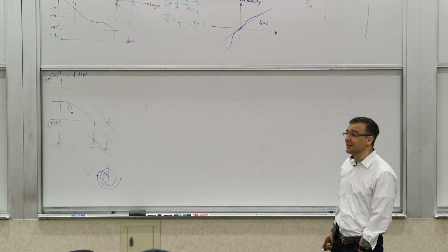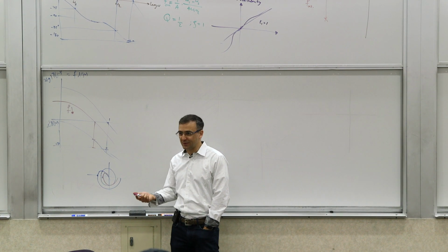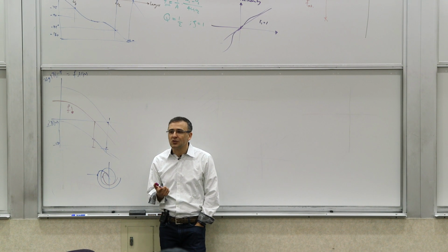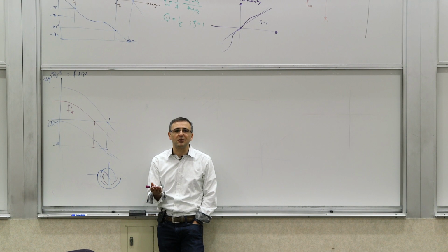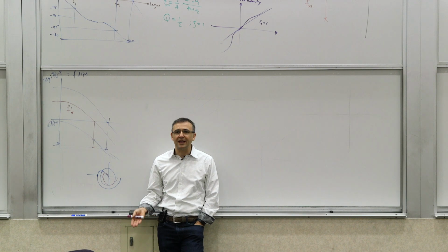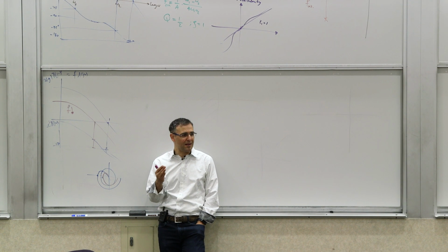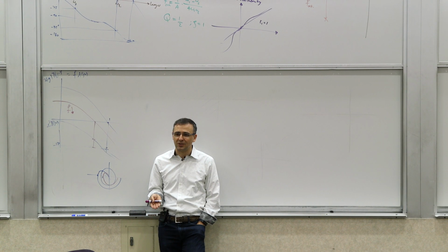Well, you get more gain. You might get more closed loop gain. You get less loop gain. That's right, right? So what's the problem with less loop gain? The question is, why did we start using feedback to begin with? Smoothing out nonlinearity, increasing bandwidth, all the advantages of feedback. So yes, you're getting less of those advantages.